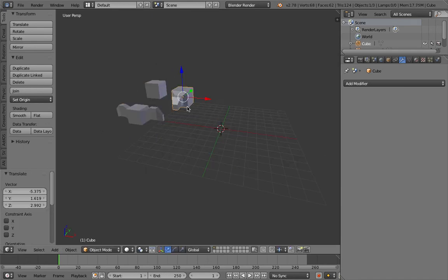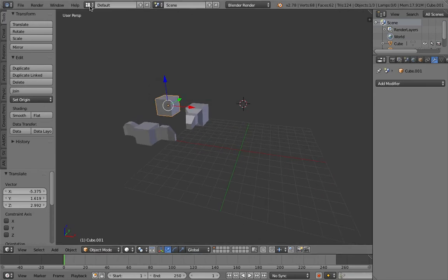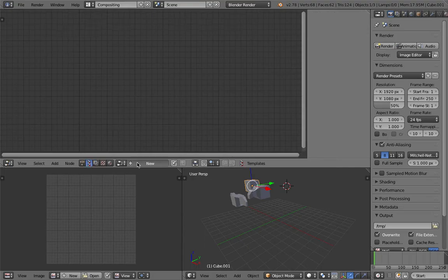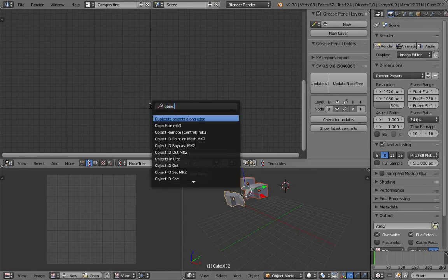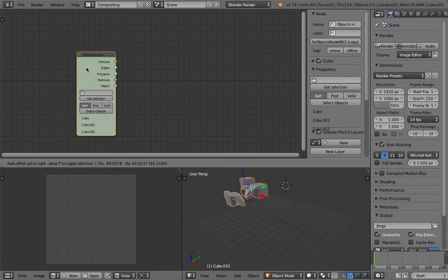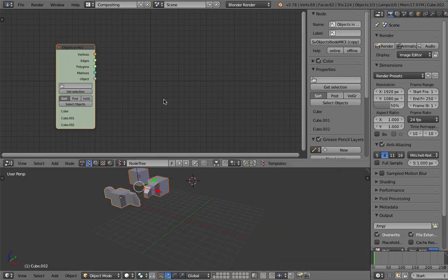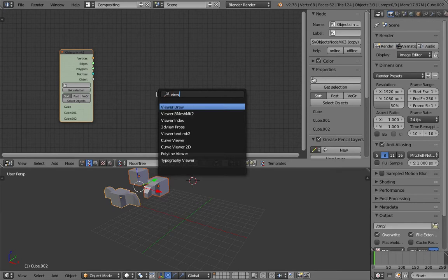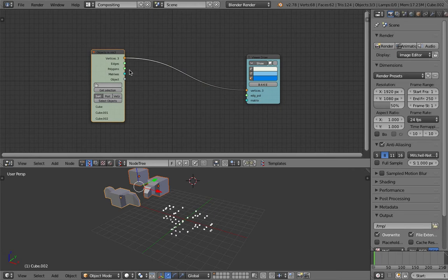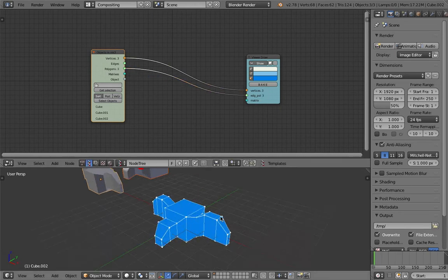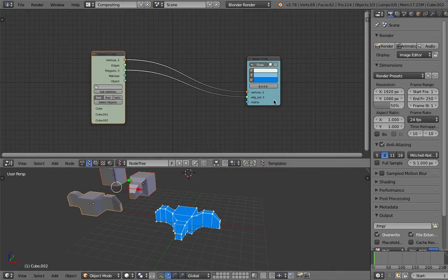We can always add elements as needed. But let's get started inside Sverchok and just grab these three guys using Objects In, get selections, and it's gonna be the elements for the totem. And first of all, we're gonna view it. Let's have a look. Okay, this is all three totem elements together on top of each other.